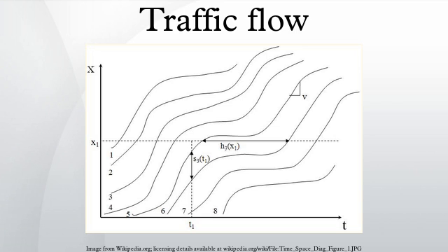Most large models use crude simulations for intersections, but computer simulations are available to model specific sets of traffic lights, roundabouts, and other scenarios where flow is interrupted or shared with other types of road users or pedestrians. A well-designed junction can enable significantly more traffic flow at a range of traffic densities during the day. By matching such a model to an intelligent transport system, traffic can be sent in uninterrupted packets of vehicles at predetermined speeds through a series of phased traffic lights.